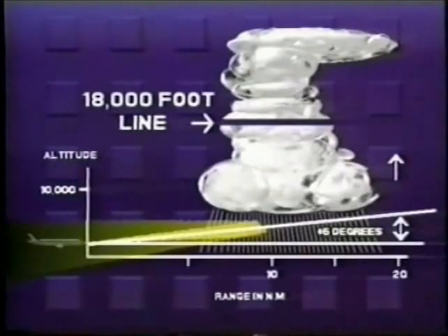On final approach, adjust tilt to 6 degrees up, using the 10 or 20 nautical mile range. This will allow the radar beam to safely scan the terminal area for weather activity, while eliminating ground returns and minimizing the radar workload. Evaluating weather should be an ongoing process until the landing is completed. Keep the radar display in your view and be prepared to initiate a go-around if threatening weather appears on the scope.